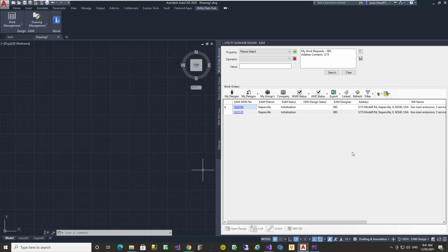Refresh is self-evident, it just refreshes the grid. These last two options are more for the evaluation version, and I'll go through that a little later in the demonstration. We'll be able to select between being a plain user and an administrator and how that affects the security. We have the ability, of course, to lock down AutoCAD commands, AutoCAD menu options, as well as plugin commands and menu options.